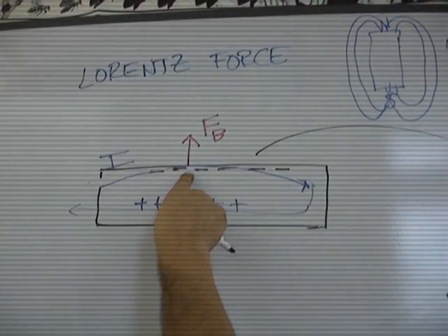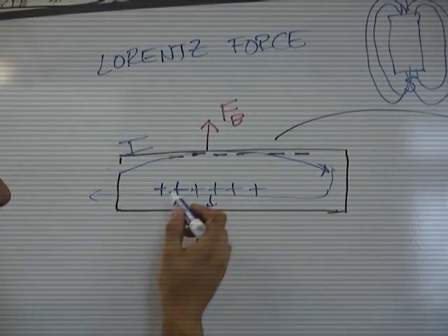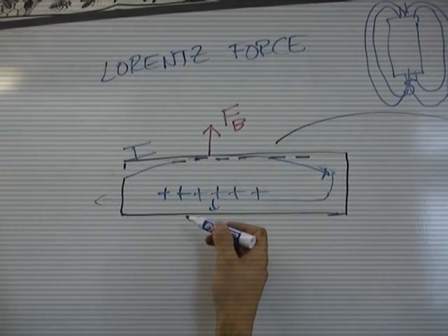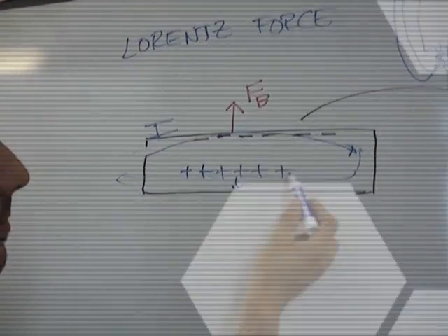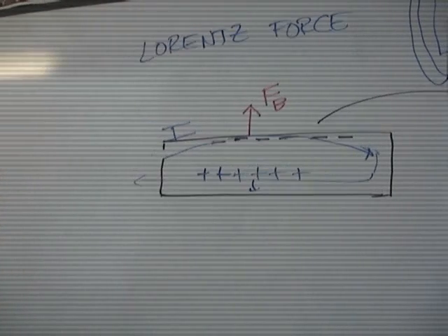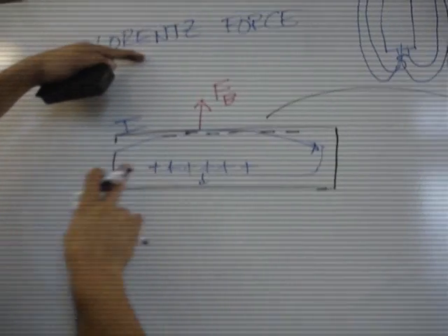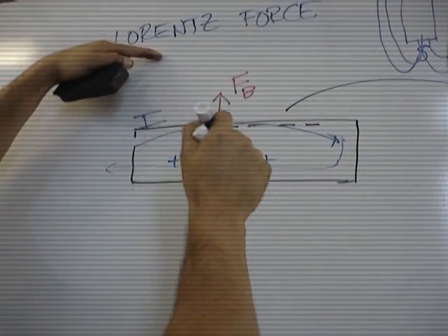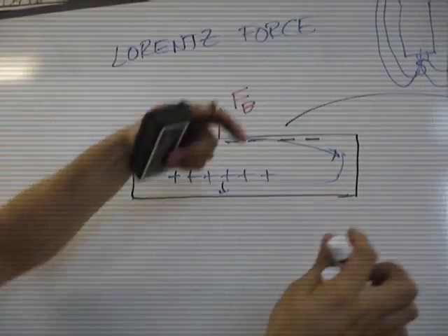And the idea is that this actually is what generates a voltage. By placing similar charge on a surface, you build up a voltage. And here we have a similar negative charge on one surface and similar positive charge on the other. And so therefore you get a voltage. This whole effect is called the Hall effect, and it's based on the Lorentz force, that when charge moves through a semiconductor in the presence of a magnetic field, which would often just be a magnet you could stick there, you get this spreading effect.